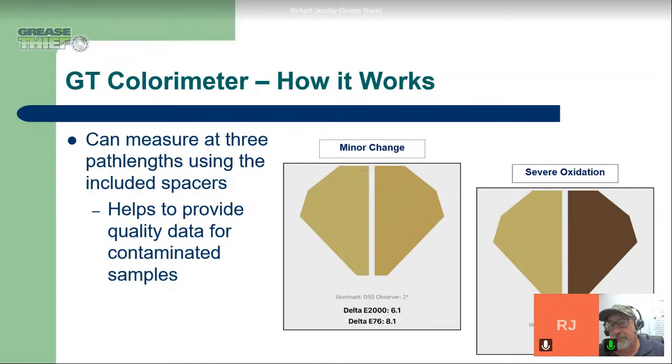Yeah, that's definitely nice, especially in robots, that joint is intended to be closed up and doing that work with that certain viscosity. So if your grease is changing drastically, and if this is a robot that is picking up a big heavy car frame or an entire large pallet of something, things can happen very quickly when you've got that large load in the application.